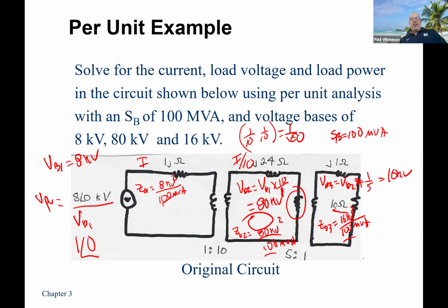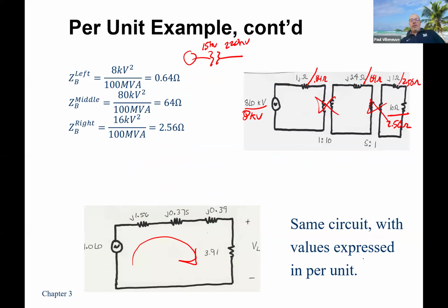And I already said, it's a fair amount of work to get here, right? Wouldn't it just be easier to go ahead and reflect the impedance up or down? So let's reflect the impedance up through here and then down through here and do our calculation, because then we already know what the current is, right? The problem is, I know what the current is out of the generator. I don't know what the current is through here. So I don't know what the power at the load is going to be. I don't know what the line consumes for power.